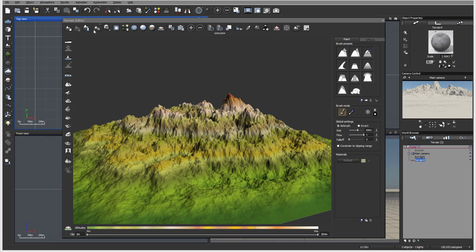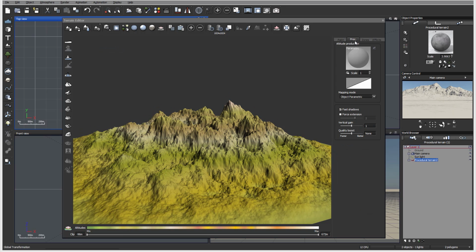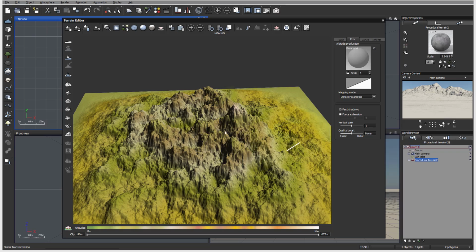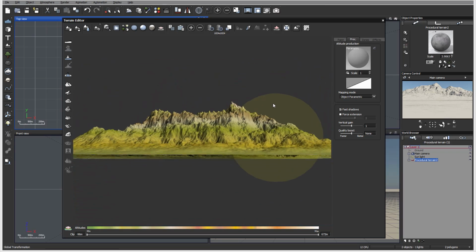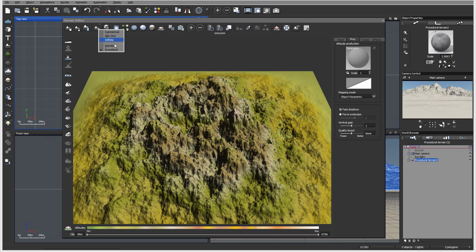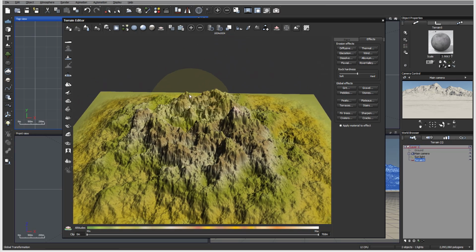Okay. Next, we also have options to create, let's uncheck this skin only. This applies when we start molding in 3D. You have standard and procedural, so you can still switch at any time. For example, if we switch to procedural, you'll notice right here, now we have our procedural parameters, zones and effects. But when you work with the function editors, be careful because it will reset this terrain, as you see. You can switch back and forth, but it will affect some shapes. So I'm going to switch back to the standard terrain that we had before.